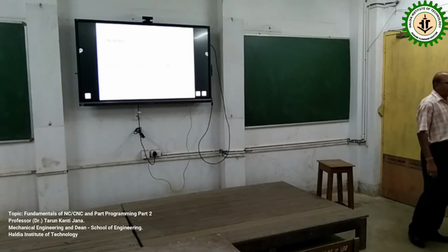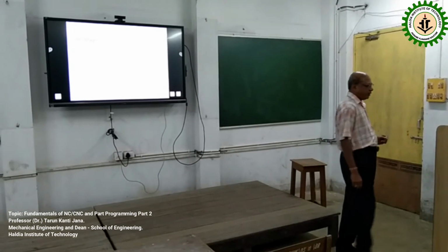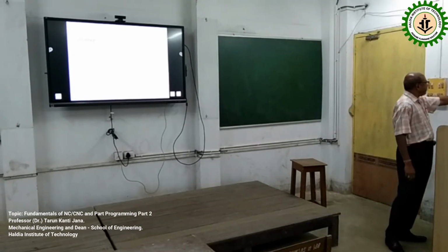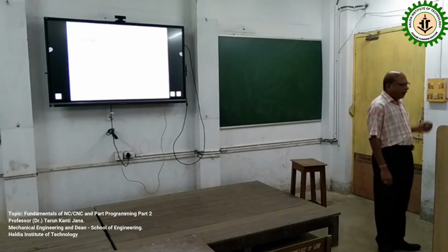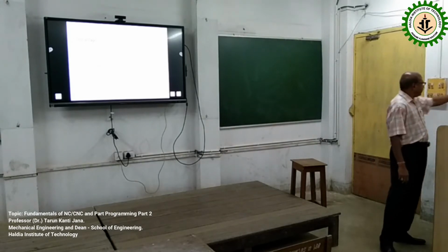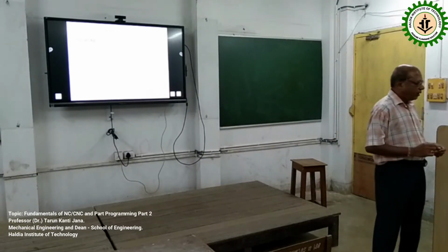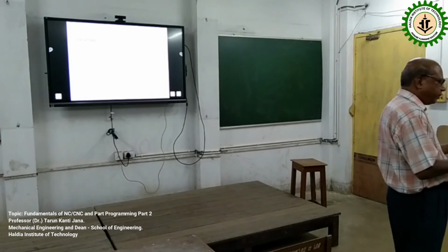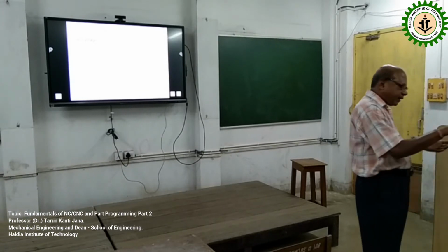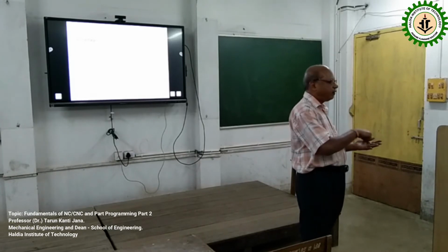On this type of item, not only 1 or 2 will be manufactured, 100,000 will be manufactured. So in that case, there is a pattern that these 5 holes have to be carried out. How will you ensure that the holes are carried out exactly at the correct location? We have to go for some marking tools, very fundamental. Give a chalk mark, take some marker, make a punch, then carry out the drilling.